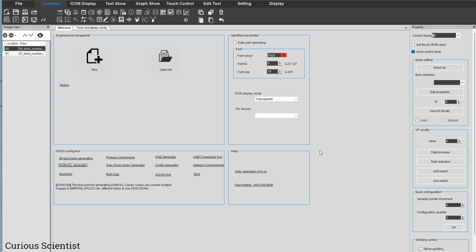So now we have everything done, and everything is in the DWIN underscore set folder. So these things have to be copied on an SD card. And the SD card has to be maximum 16 gigabytes. I have noticed that if I try the 32 gigabytes, it is not working because of the file system we have to use. It's a FAT file system and not NTFS, and that doesn't really like the 32 gig SD card.